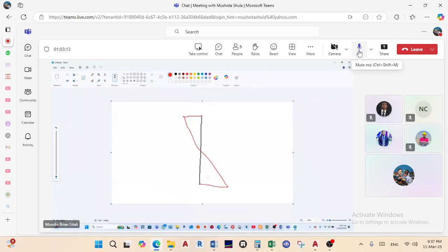What this means is that as I am going towards the top support, I have maximum shear; my shear is increasing as I'm going towards the support on either side of the column.